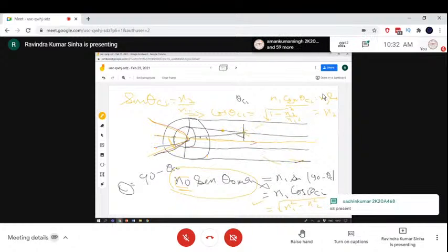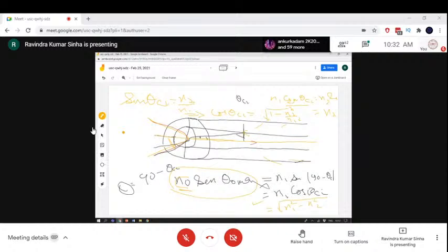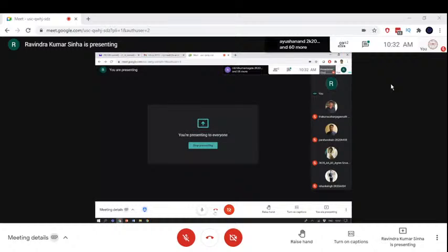So that property is called numerical aperture, that is the sine of the semi-vertical angle of the cone. N0 is here 1, that is why we can define. Okay, mathematically this is the definition. In general, that is called the light gathering capacity of the optical fiber.